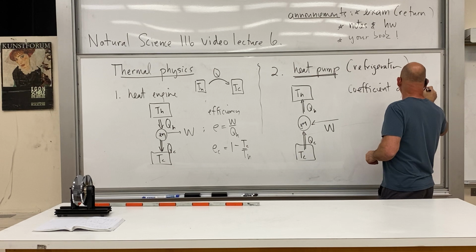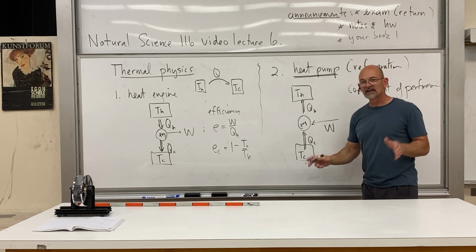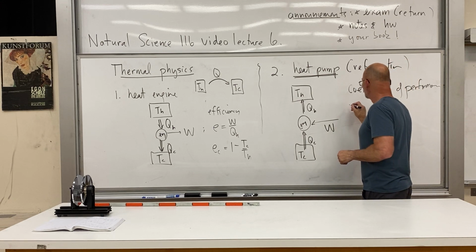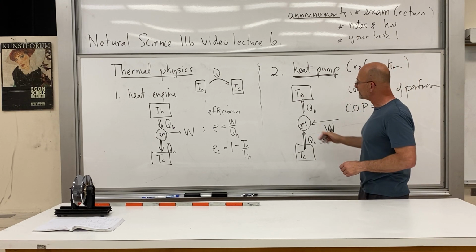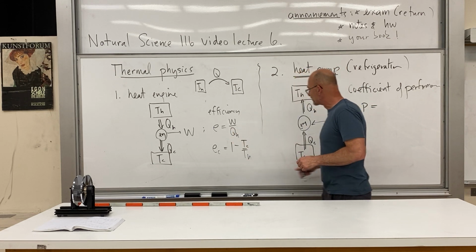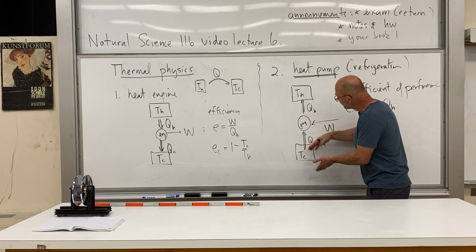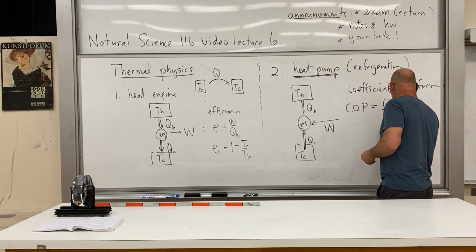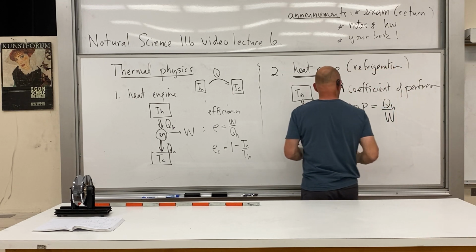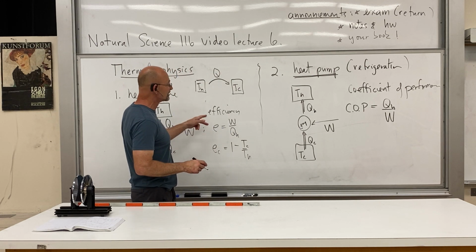Coefficient of performance. Coefficient of performance. And what that is, literally, is the inverse of this. It's namely how much energy you can bring up to the high temperature reservoir for how much work you put in. So the coefficient of performance is the inverse of the efficiency.